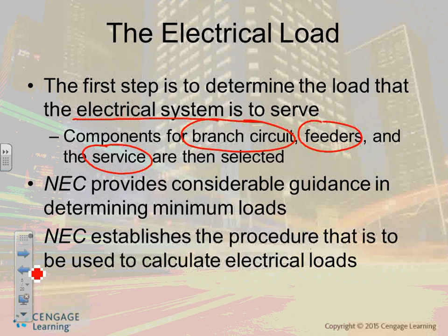Branch circuits. We didn't talk a lot about branch circuits or load calculation. We will be doing branch circuits for lights, branch circuits for receptacles, branch circuits for equipment, guys. But your load calculation must be able to answer what size of panel do I have, what size of feeders do I have, and later on, based on the load, what branch circuits do I need? How many branch circuits do I need? Can you guys see that?